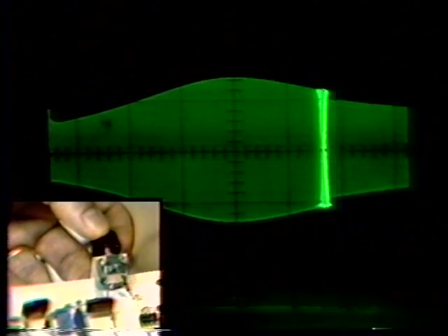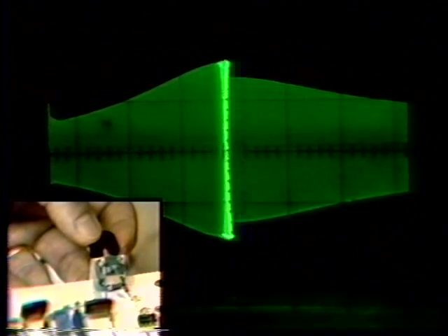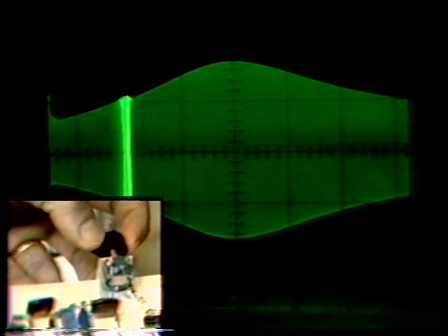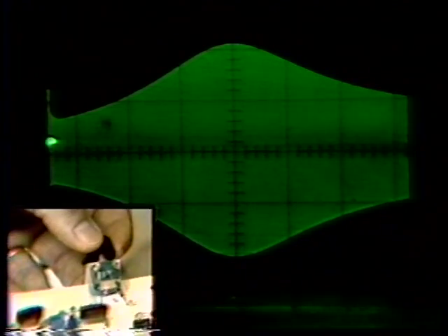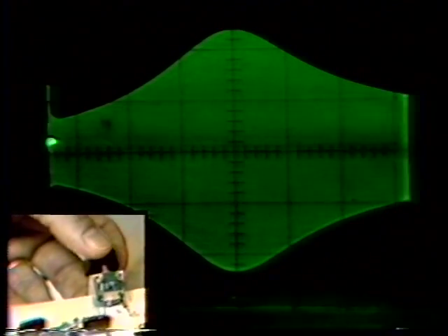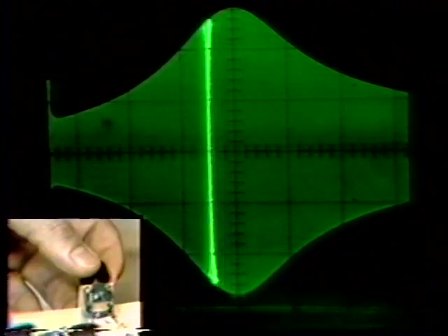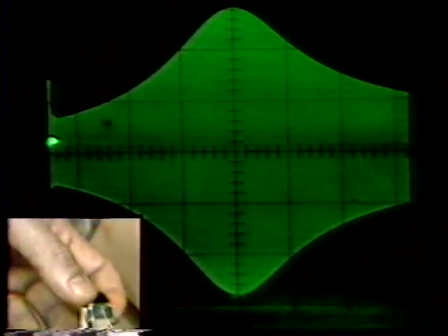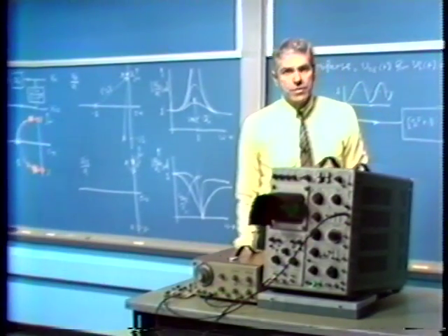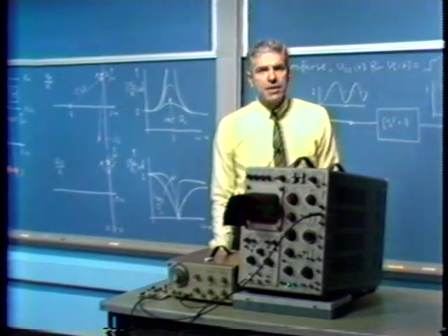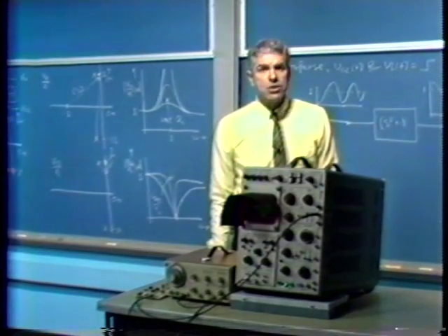Another time, and some additional A0, still more. And now we're beginning to get quite an observable peaking in the response. Larger value of A0, still larger value. And finally, the maximum value of A0 that we can get with our system. Here we have a range of A0s that only allows us to get down to possibly a damping ratio of 0.1 or so for the dominant pole pair. So we don't get a very highly resonant effect, but we certainly get a very observable one.